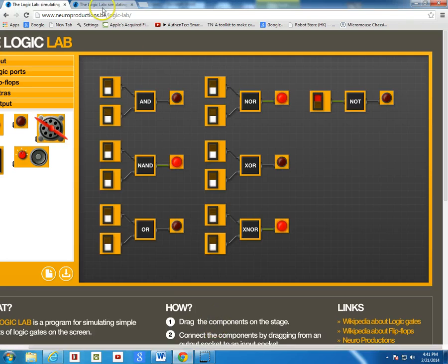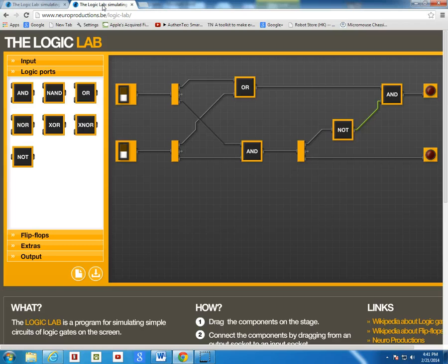All right, so let's go back now and kind of close the loop on this. I'm going to take a look at this first circuit that we looked at when we first started this tutorial. And we now see that we have these little logical gates connected with 2 inputs and 2 outputs. Now I want you to imagine that we're going to be adding up 2 bits, either a 0 or a 1 added to a 0 or a 1, and we're going to get some result, which is going to be my sum, and then down here it's going to be the carry. And believe it or not, this circuit is called a half adder circuit, and it will actually do single bit arithmetic. So this is the type of circuit that's in pretty much every computer chip processor that's out there.